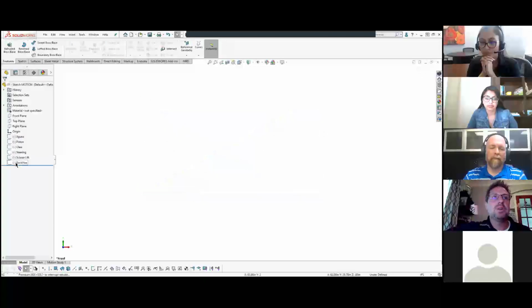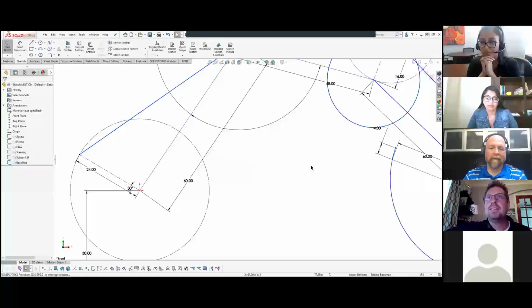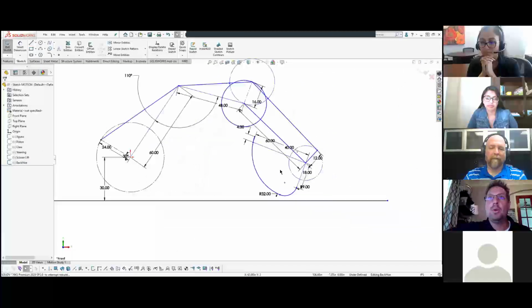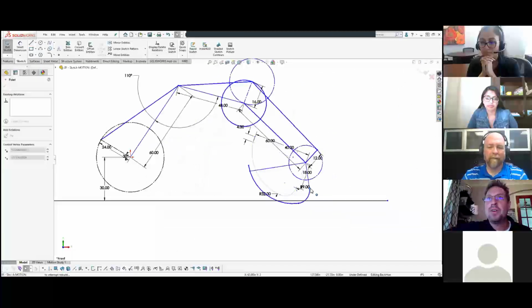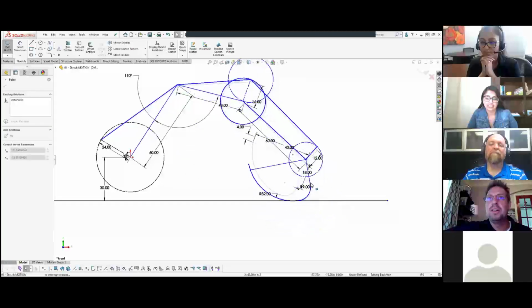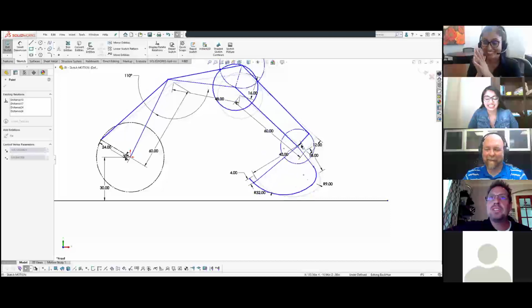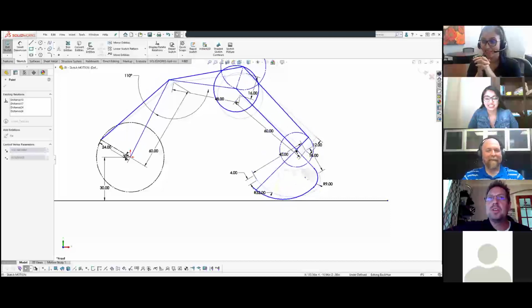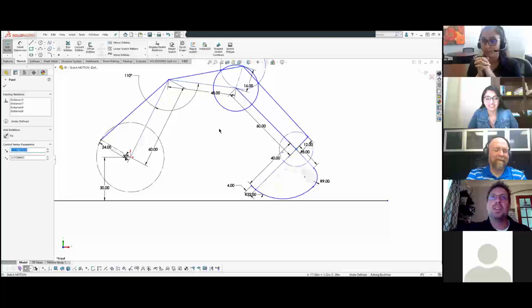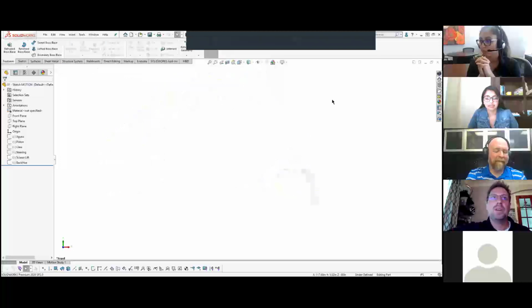All right, last one. This one gets a little bit crazy. This one actually took me a while. I tried to model up a little bit of a backhoe. If I start to grab this, and it may get a little wiggy, you can see I can start digging up some of the dirt here. And you've got to make machine noises. Then you can drag some of the other actuation things. Again, really what you're trying to do is figure out what's my min and max on where you can move and make things happen and work right, so that you get planned out real quick in 2D, and then, of course, you go to 3D.